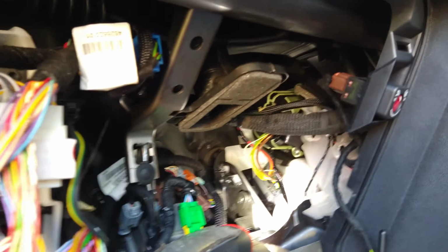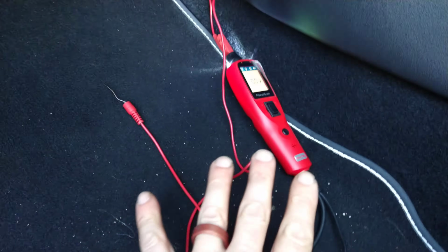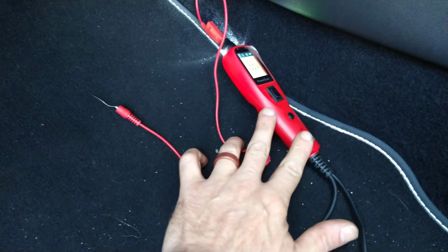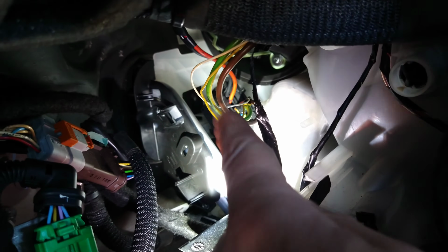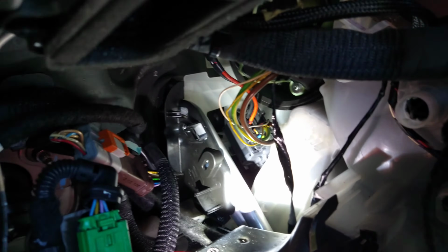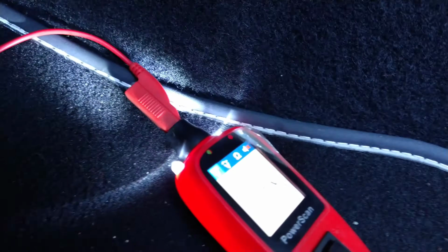I've removed the glove box that was here and the cover under here. I'm going to use the test light. I've taken out the tip and put a wire in, so it gives me better access to get to those wires there and start doing some checks. Hold on, try and think how I can do this better. Without a wiring diagram, I just work my way down the wires, and I'll tell you what they say. Well, it's 12 volts.